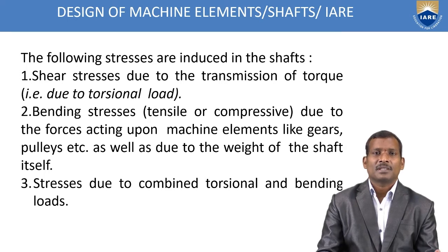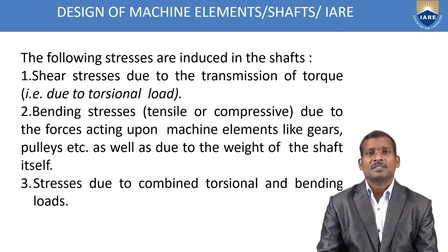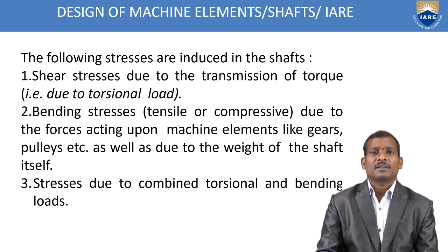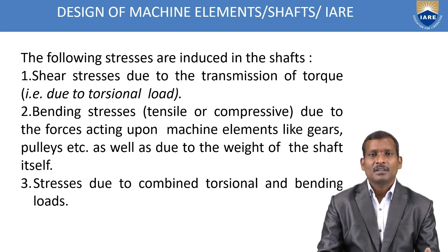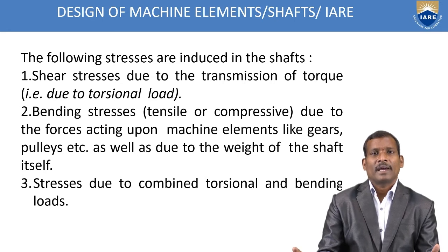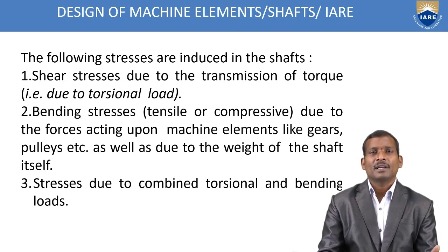One is the maximum shear stress theory, another one is the maximum principal stress theory or normal stress theory, you can say Rankine's theory. The maximum shear stress theory is also called the Guest theory. Before applying those theories, you should know what are the basic stresses induced in the shaft due to the various loads.